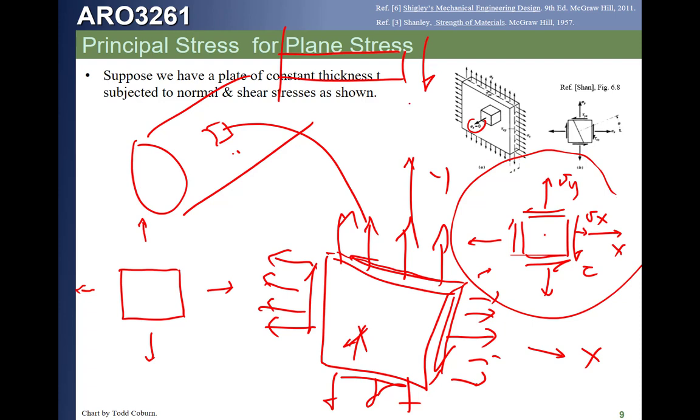We will still use that nomenclature for any kind of beam-like things, but when we're talking about shear elements, we usually call a positive shear stress on a little shear element that's not chopping off a beam positive in this orientation. Really either one, and this is a tau here. So this is sigma x, sigma y, and tau.